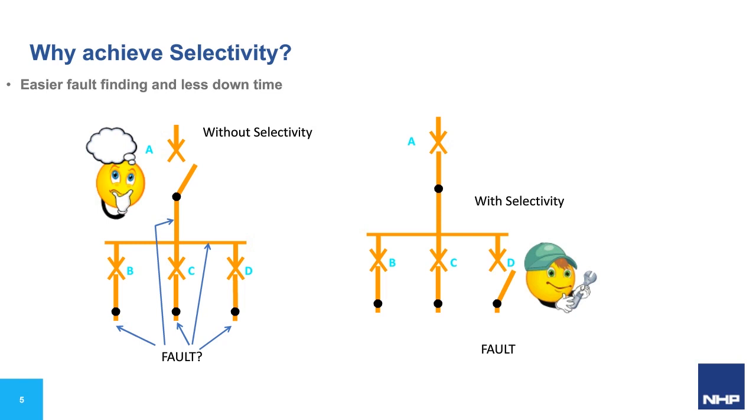It is not only the issue of loss of power in these instances. The time taken to safely investigate the root cause, rectify the potential fault, and reinstate the supply may cause process delays, cause quality control issues, and potential wastages, as well as possible data loss because of inadequate backup systems such as UPS providing ride-through or backup power. In the case of equipment such as transfer switch operation, an upstream circuit breaker trip would cause a system lockout and deny backup transfer switches from closing onto a potentially faulty circuit.